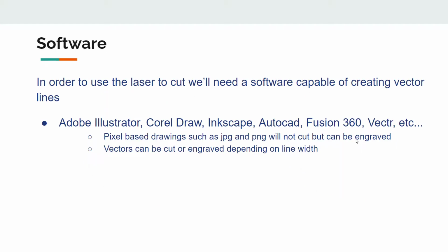Okay, so as I said before, in order to use the laser cutter to cut shapes, we'll need a software that's capable of creating vector lines. In the makerspace, we have Adobe Illustrator, but you can use a number of different software, including CorelDRAW, Inkscape, which is a free version of Illustrator, AutoCAD, Fusion 360, or any type of CAD software. Now remember, pixel-based drawings such as JPEG and PNGs, these will not cut, but they can be engraved. So you don't necessarily need a vector software in order to be able to just engrave something in the laser.